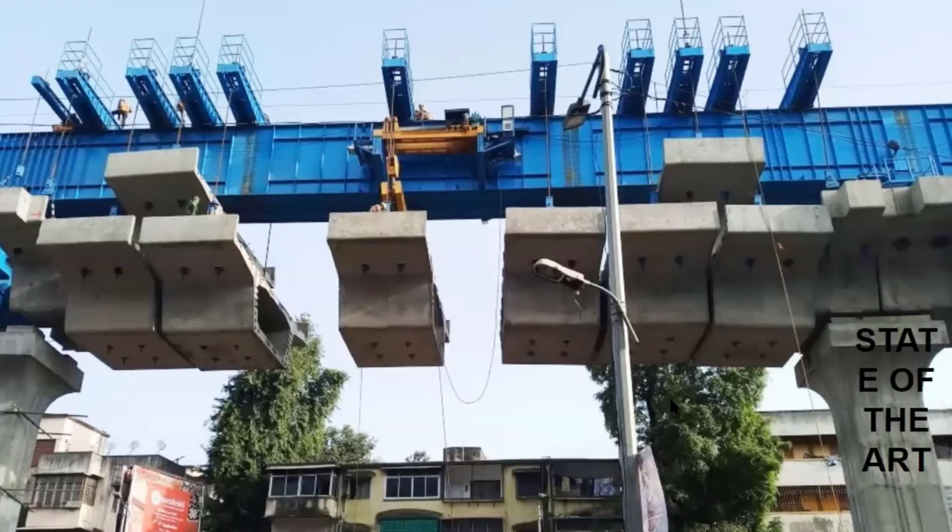Now you see, in the course we will be understanding how to design this kind of a structure, because when we design a structure, we need to take into account the loadings on the structure during all stages of its life. By its life, I mean from the day it is cast to the day the bridge goes out of service, which is about 100 years of time. So during these 100 years, it will be exposed to various kinds of loadings: wind loadings, seismic loadings, the metro running on it regularly, as well as the loadings during the construction.